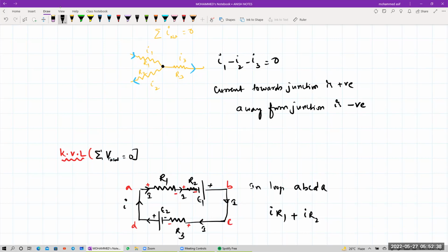Now the battery is coming. Whatever first it comes with, I'm taking that one. So the battery terminal is first negative. So it is minus E1. Then again in the same direction, plus I into R3. Then again first negative terminal of the battery, minus E2 must be equal to 0. Done? Yes, sir. Same direction also, name this positive. Yes, sir. You can even take negative, beta. If you are taking negative, then the cell should be taken wherever I'm ending, that will be my sign